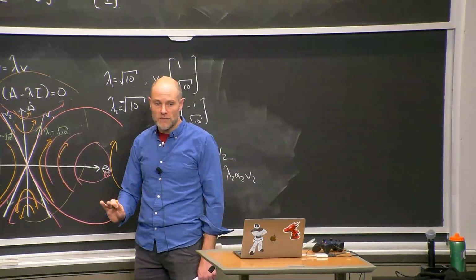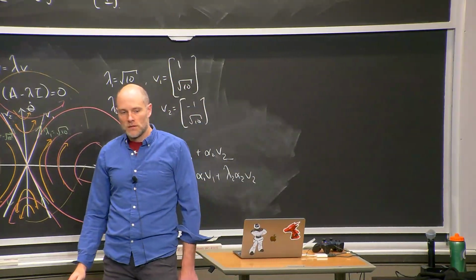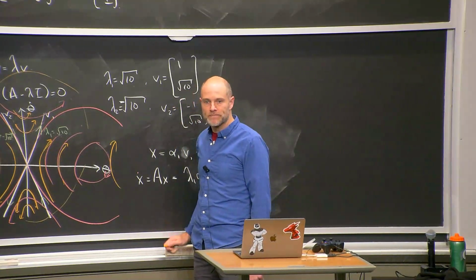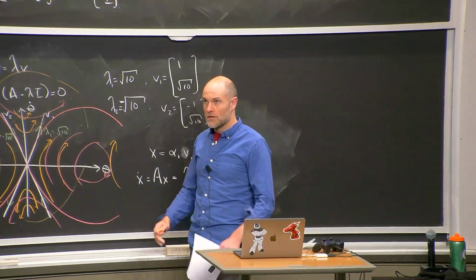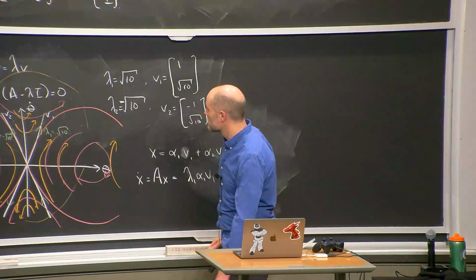The condition on the eigenvalues in continuous time is simple. It's just less than 0. Left half poles is the classic feedback way to say that. And then if it's a discrete time system, you have to be less than 1. That's the inside the unit circle condition.